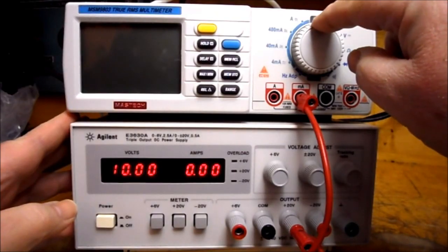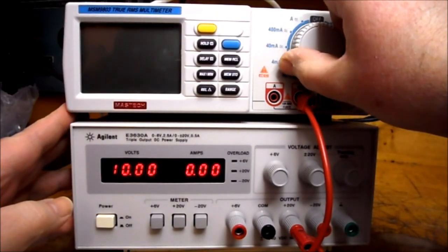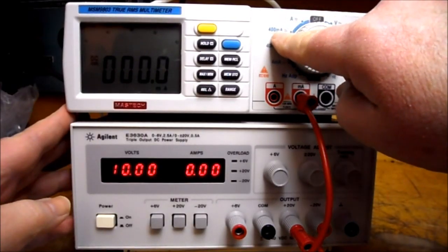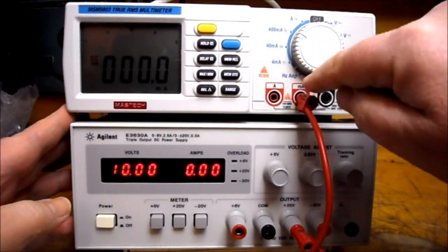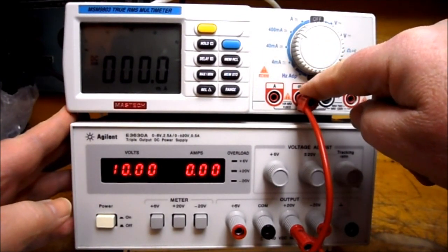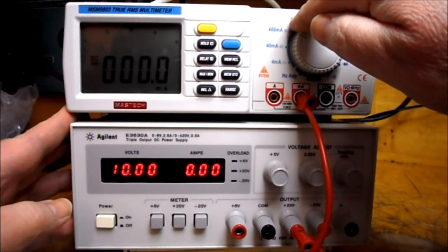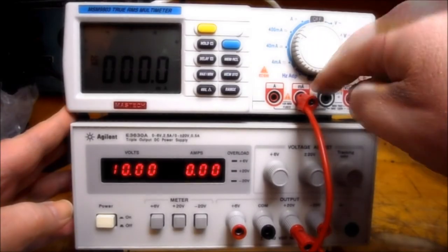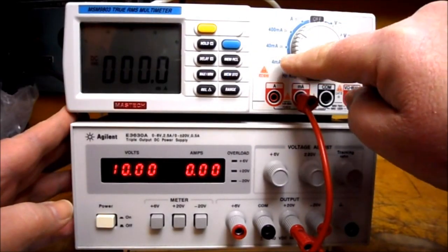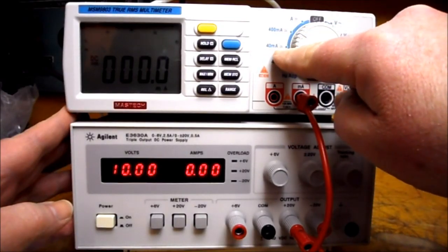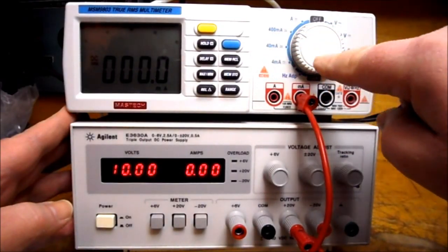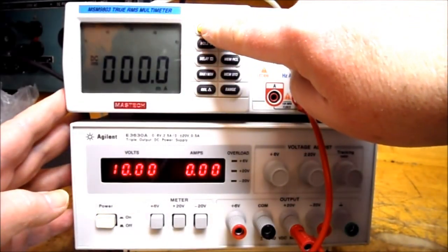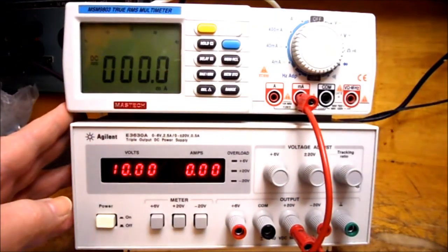We're going to set our ammeter, and our ammeter is all manual ranges, so we're going to set it to the highest range possible. In this case it's the 400 milliamps because we're using the milliamp hole. If we were to use the amp hole, we could only use the A range on the digital multimeter. So we're using the milliamp terminal. So we have to select the range as 400 milliamps, 40 milliamps, or 4 milliamps. So you always start with your highest range, and you can put the backlight on for the display if you can't see it.